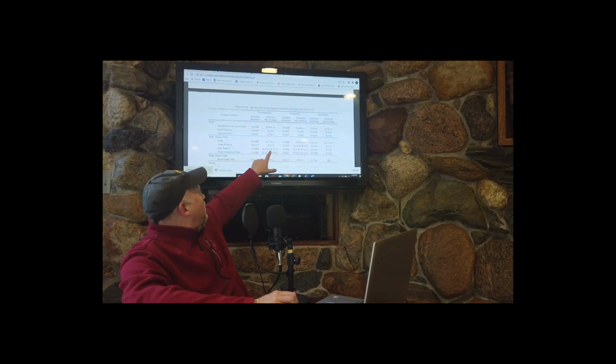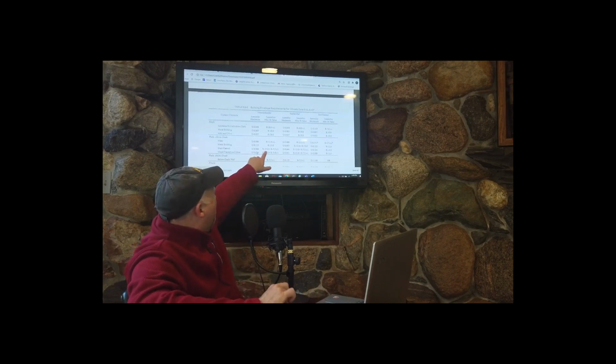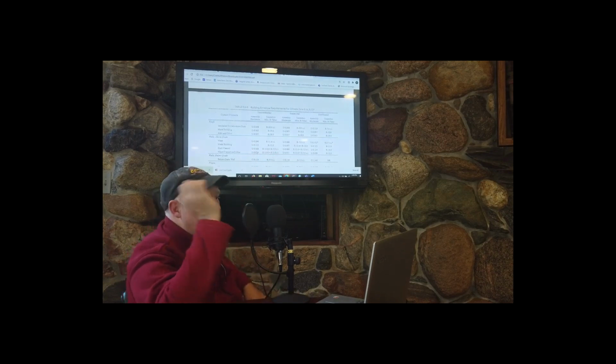Look at steel framed. Now, this one is interesting. A U value of 0.064. Now, what you'll notice is that if you add this R value of 13 plus an R value of 7.5 continuous, and then take the inverse of it, it does not equal 0.064.